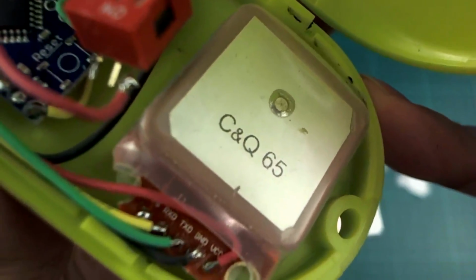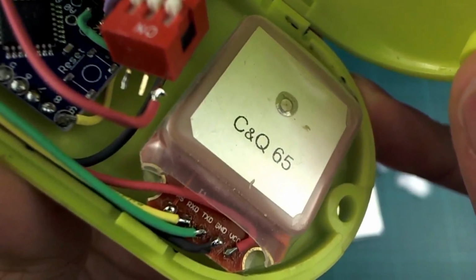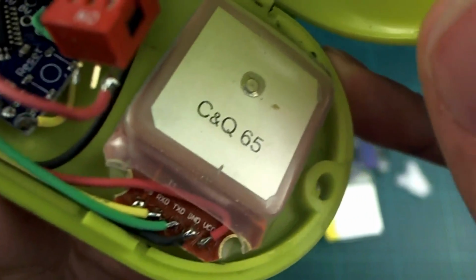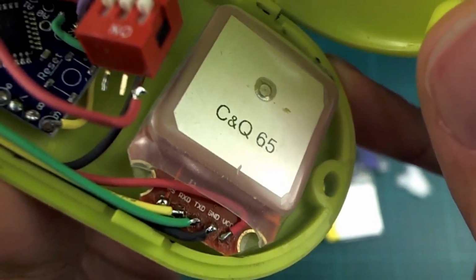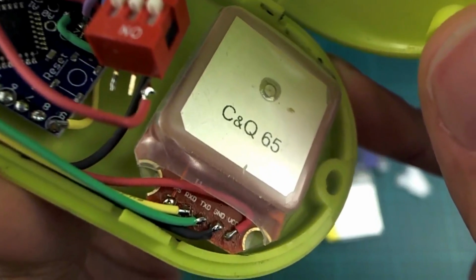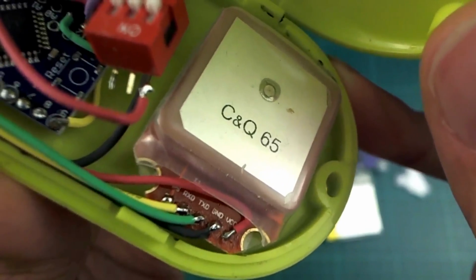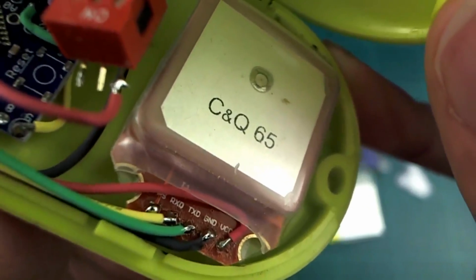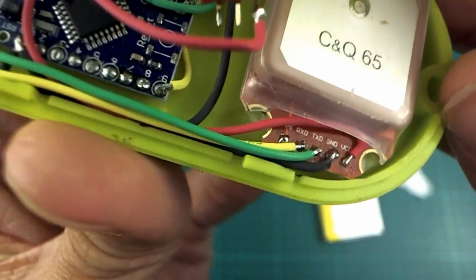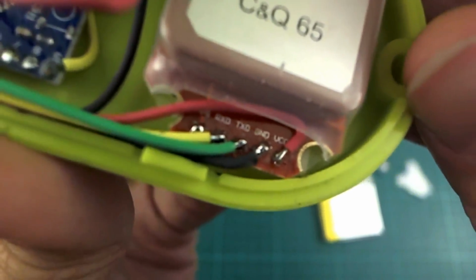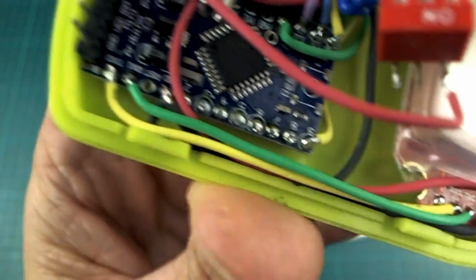And then down here I have a U-Blox, or U-Blox compatible, I think. I'm not sure if it's an official one. And this is a Neo 6 series, so you don't need to have the 7 or anything newer. A couple of my other sketches that I've uploaded were made for the 7 series, and people have been asking me questions about why it doesn't work with their Neo 6. But this one will work with the Neo 6, so we shouldn't have any problems like that. And this is a serial connection, so we've just got the RX and TX there, and power of course.